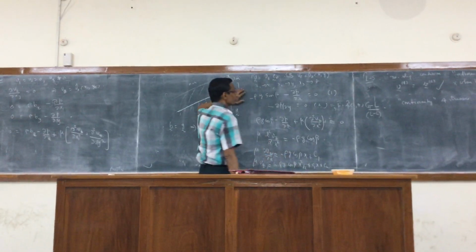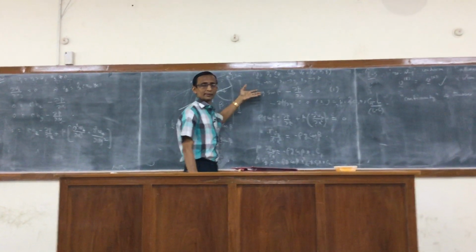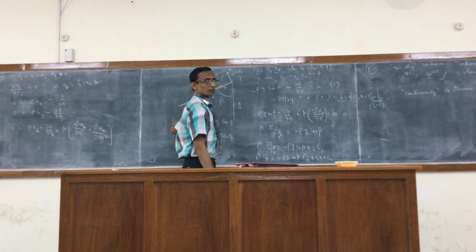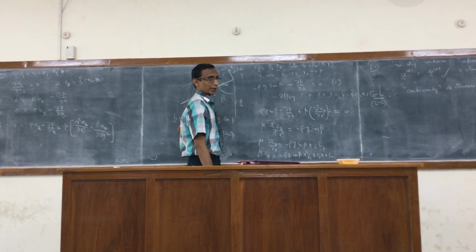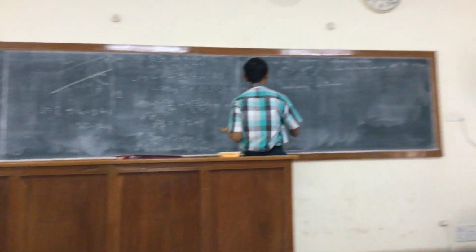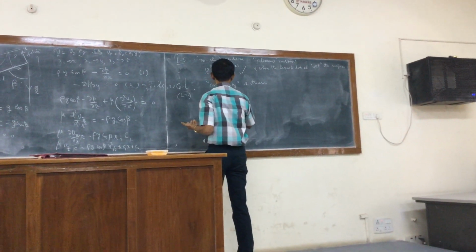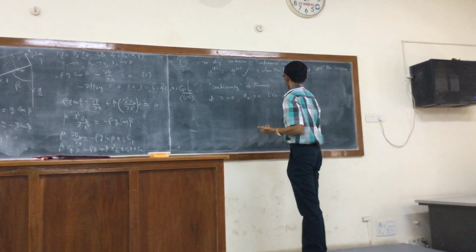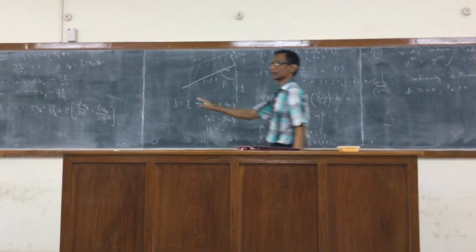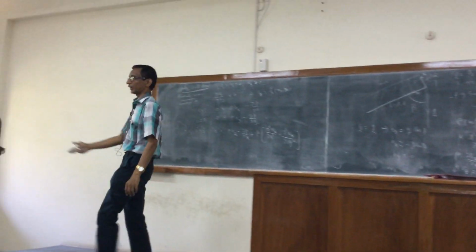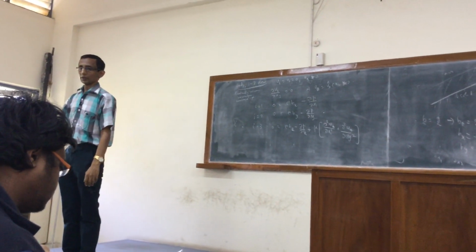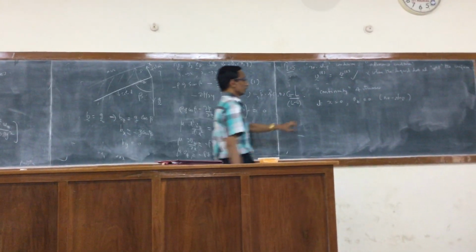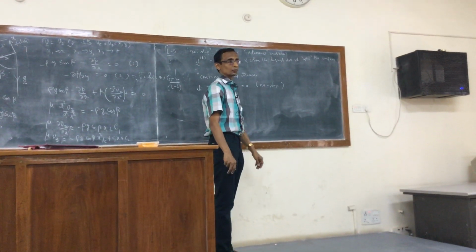Now, how does it apply here? That is very easy to infer, right? The first condition, especially that the plate is not moving; it's an inclined plane, right? It is fixed. So clearly, at x equal to 0, v_z equal to 0, that would be the form that the no slip condition will take. We are not considering those anomalous cases. The fluid might not wet the surface and all those things, be set aside. So this is clearly the no slip condition. That's how it would apply.